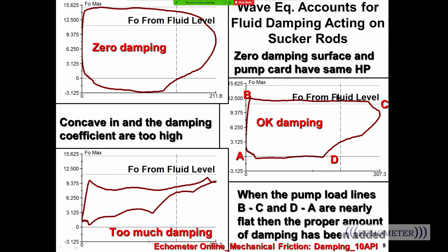And this pump card right here on the right shows that the load on the upstroke is fairly flat, and the pump load on the downstroke is fairly flat and resting on zero. And you'd say, well, the damping factor is just right.